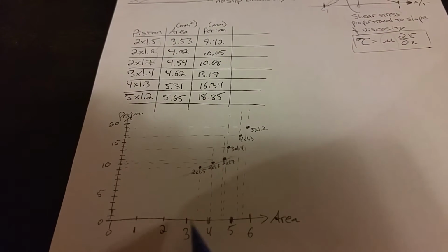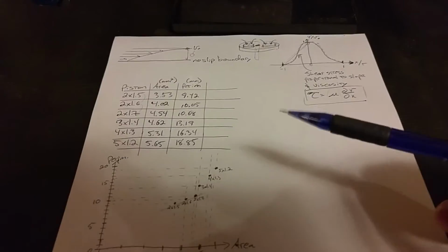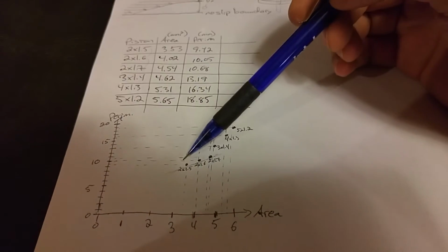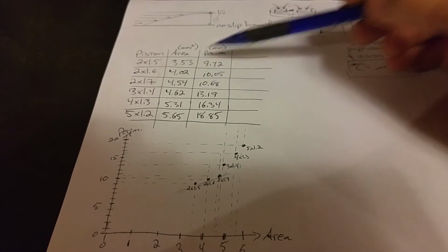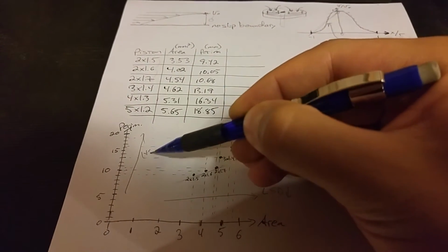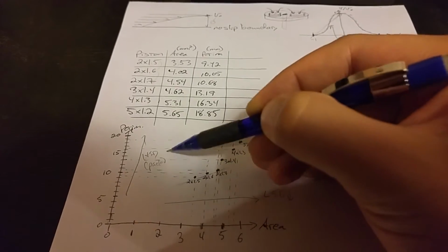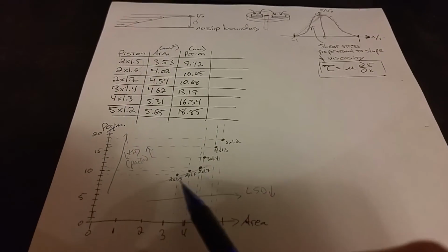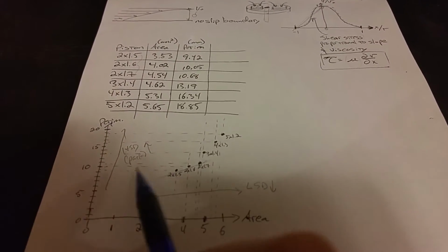Okay, so I'm increasing the total area, which means that my low speed damping for cornering is lower, so the shock is effectively lighter. And at the same time, the total perimeter is increasing. So as I move along in this direction, low speed damping drops, and as I move along this direction, high speed damping or pack increases. Okay, so basically I'm moving along a particular curve for low speed damping and high speed damping.